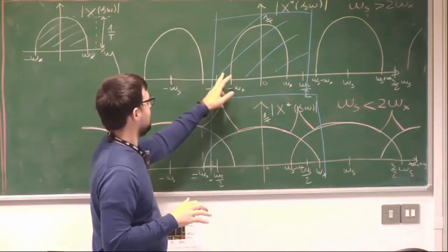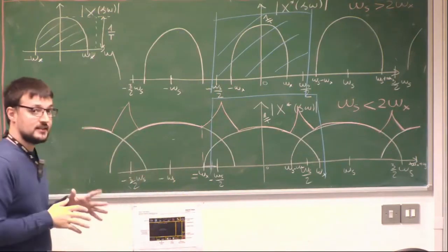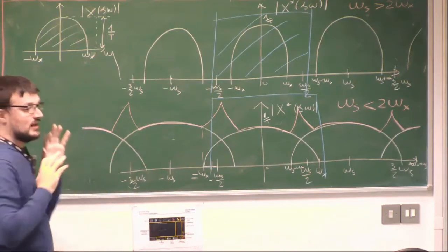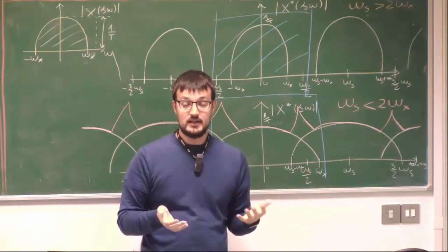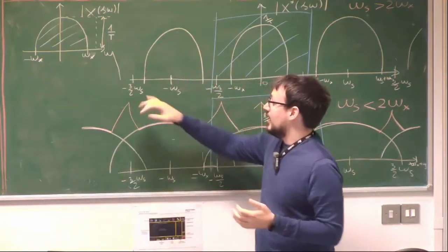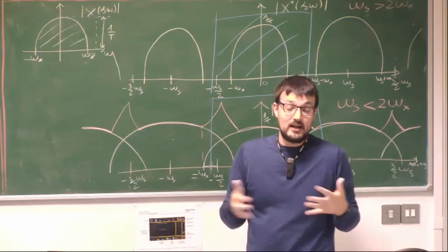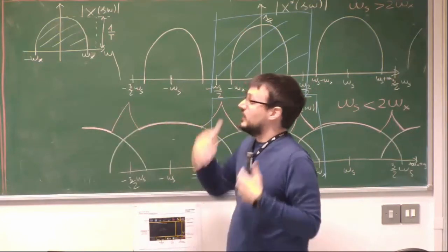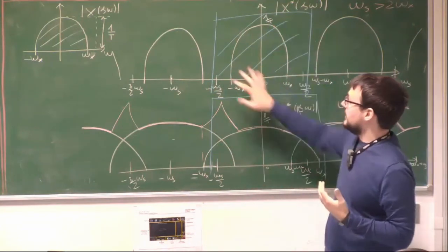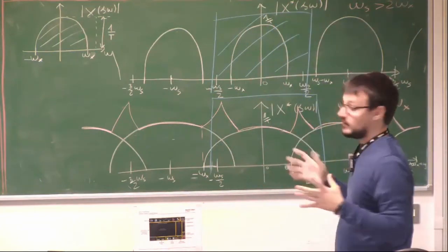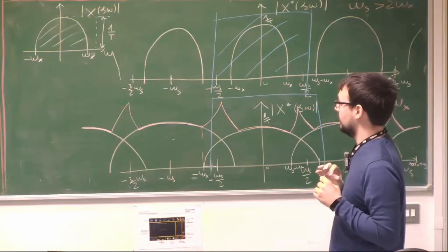Now, why did I say maybe we can reconstruct the signal? Okay, there are two things to consider. One thing is that in control systems, this situation in which you have a maximum frequency is very rare. The reason is that in practice, for instance, our signal will have some noise. If you have noise, noise usually appears at all values of frequencies, so it's unbounded in frequency, so this means that we cannot actually apply the Shannon theorem, okay? The other question is that this type of filter is ideal, and you cannot actually build an ideal filter, and we will discuss this very briefly now.